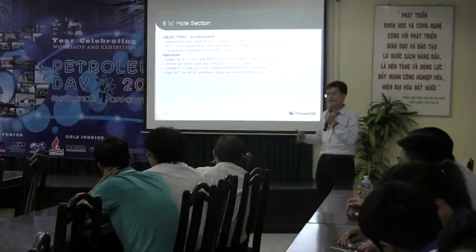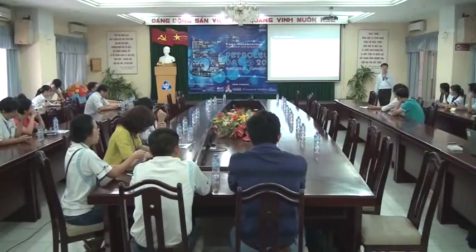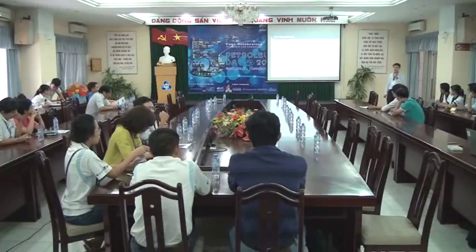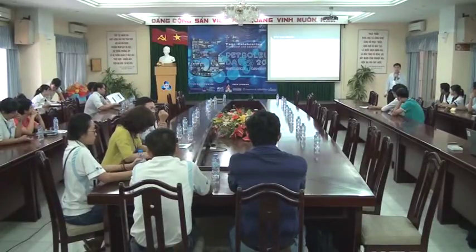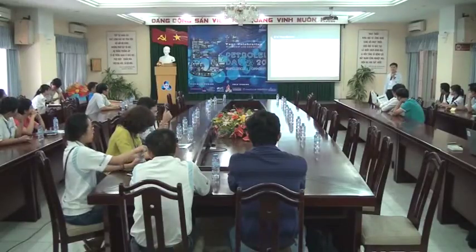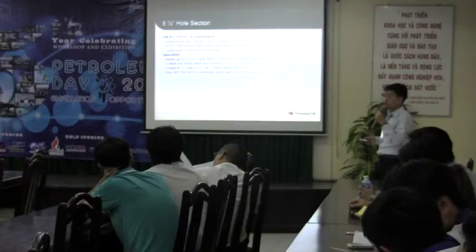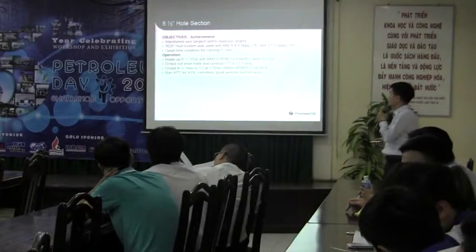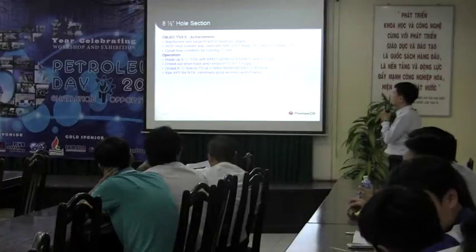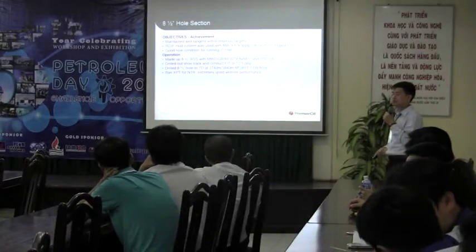That's why it needs to be very specific for the production hole, like the special mud for the production hole, and all kinds of that. We have to take care of that. However, the operation sequence is the same. We make up the BHA and drill out the shoe track, conduct the FIT, and drill down to the TD.